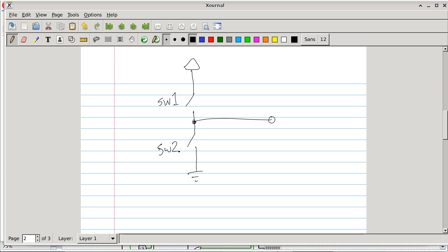So are we okay now understanding what the word floating means in an electrical circuit? Now, is it a bad state? Not necessarily. If this point here is not being interpreted, it's okay to let it float. It doesn't really matter. On the other hand, if this point is actually connected to something and something is actively trying to interpret whether this is a 0 or 1, then floating is not a good idea, because it can pick up a 1 at one point, a 0 at another point. You have no idea what it is going to pick up. Is that okay?